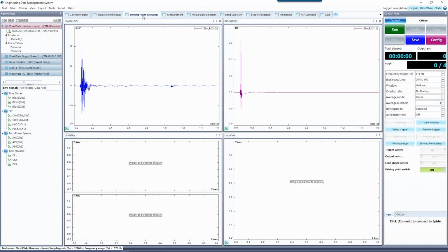By going through 20 times, you can finish a 40-point measurement. And of course, for the input mode, I'm using ICP sensors, so IEPE should be turned on. So that's the input channel setup. Not too much to talk about, but keep in mind the DOF setting is crucial. Every FRF measured associated with the channel will have a label for that DOF, and that associates the measurement to your geometry.